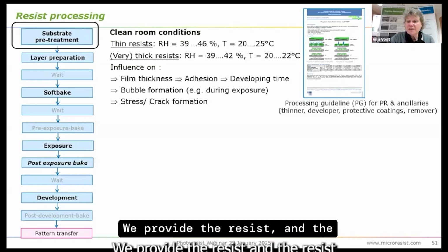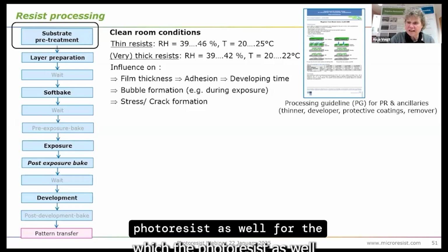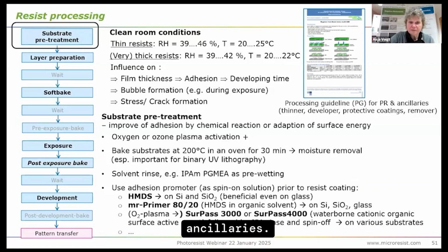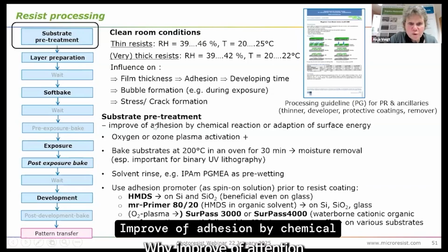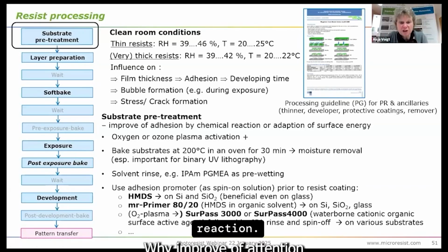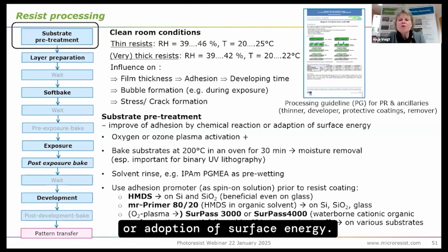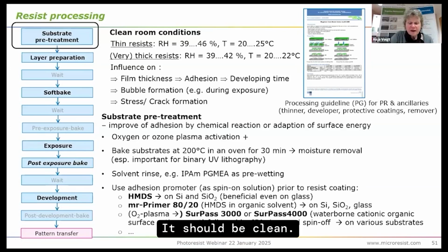We provide the resist, and the resists come with a processing guideline for the photoresist as well as for the ancillaries. Substrate pretreatment, why? To improve adhesion by chemical reaction or adaptation of surface energy. It should be clean.